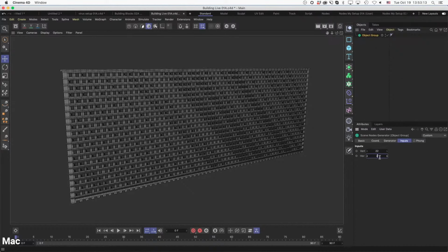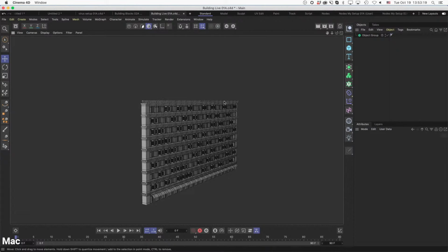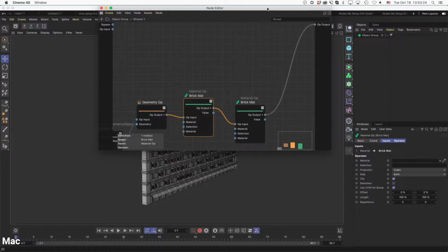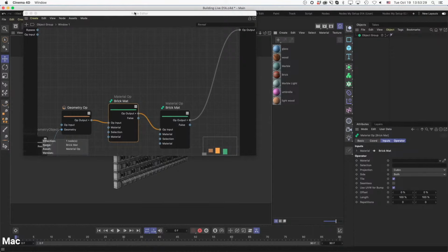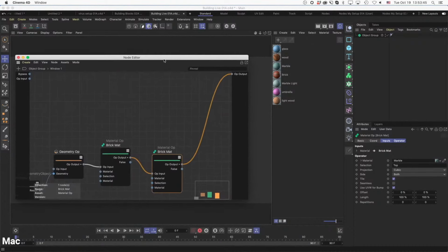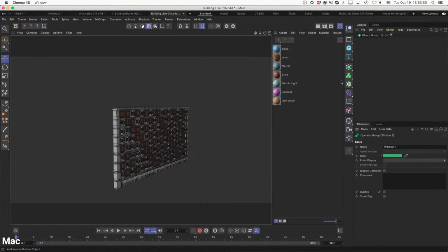So let me read some questions here, and I need to check out that material thing. It may be some temporary limitation. It's lost its links to the material. So that copy paste broke that. So let's see if this is going to work. And this is brick, and this is brick, and this is the top. So it's marble, and it's working. You can see that everything is working. So yeah, if you take your time and go in these and reattach the materials, there you go. You have an asset with materials and all that.